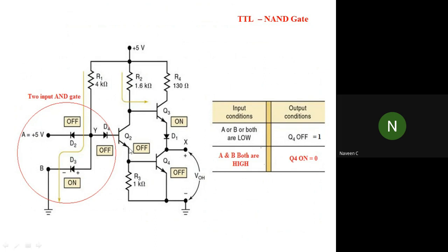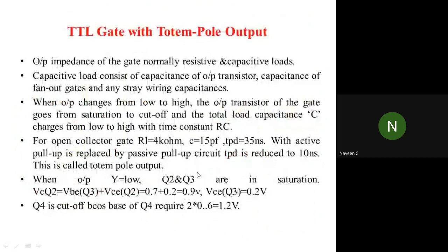So it is like your previous logic. Here you are giving high voltage, and here also high voltage. If both are high, it will automatically go to ground. Whenever any one of the inputs is low, the ground path is avoided and the output comes through this diode.